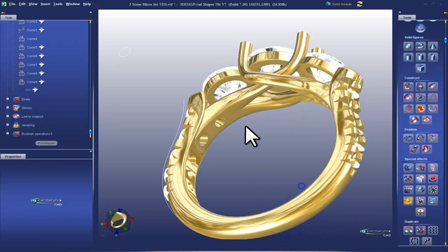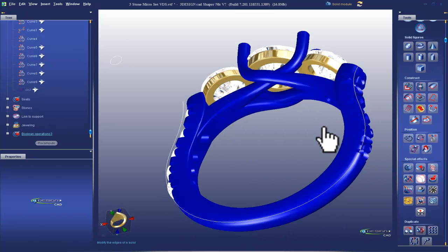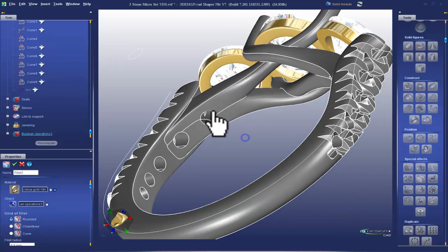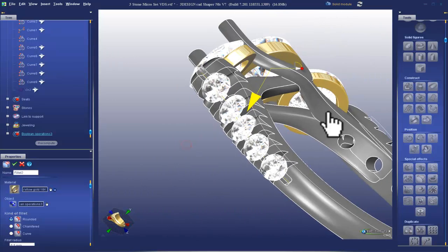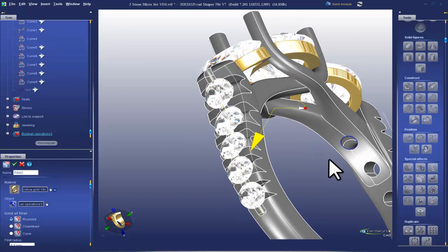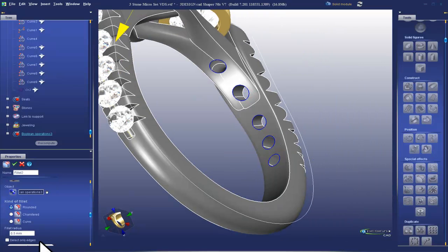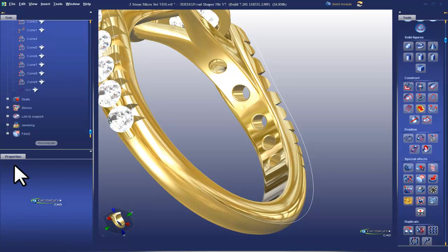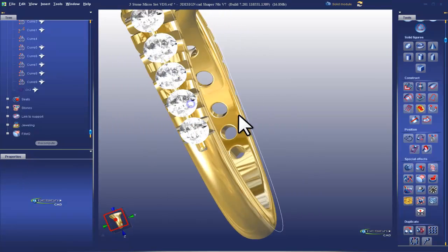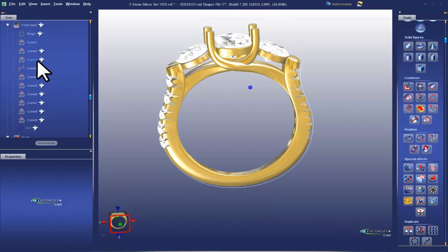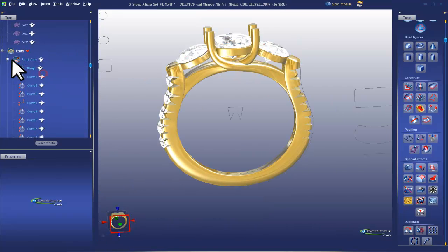Add a couple of last little details. We'll add a fillet. Try adding one to all of the holes. I'm going to try with the smallest fillet, 0.1. And hopefully that flies. Great, it added a nice fillet. I'm going to hide my entire sketch.